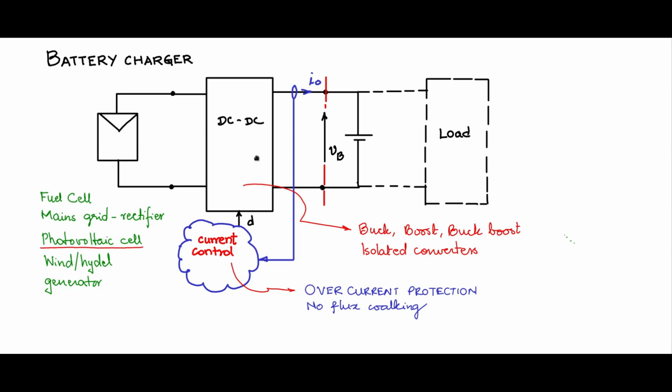So this photovoltaic cell is used to charge the battery through this DC-DC converter, and the DC-DC converter will be a buck converter that I will be using. You can use any primary converter, and we will be sensing the output current, which will be the inductor current, and use that to control the current of the inductor. So let me mark this. This is the terminal voltage of the source. IPV is the input current to the DC-DC converter.